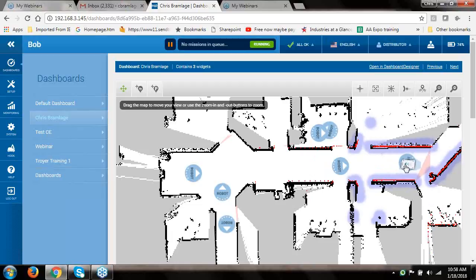So in the hook manual, you'll notice that there's a maximum height for a cart of 2 meters, and the extension of that 3D camera goes up to 2 meters in front of the robot, just to make sure you don't go under any low-hanging items that could be hit by the cart itself behind it. All right, that's the basics of that portion of it. I think we'll get into some of the menu items now. We're currently at about the 11 o'clock position, so I'll take one more look at the questions. And seeing none, I'm going to continue.